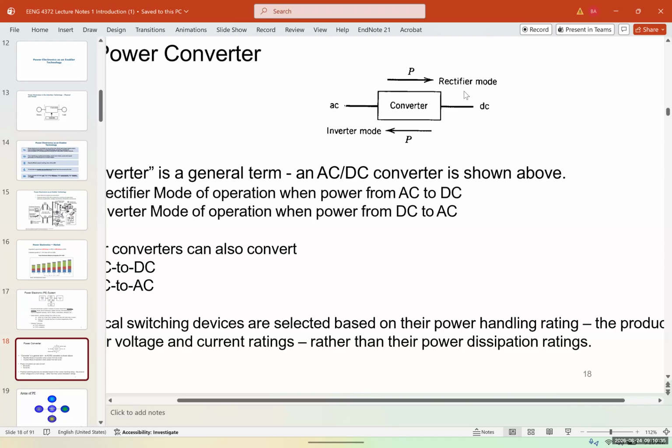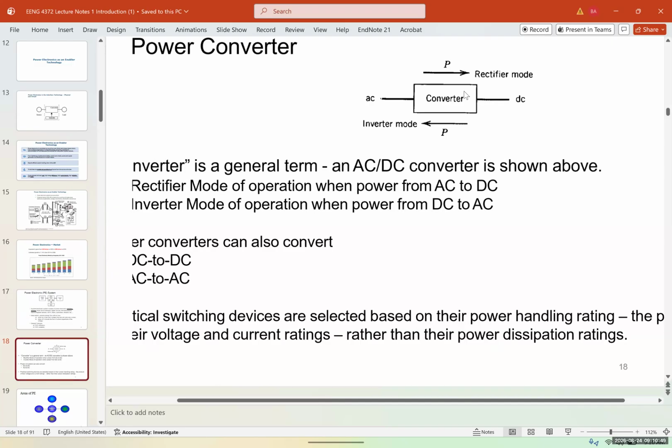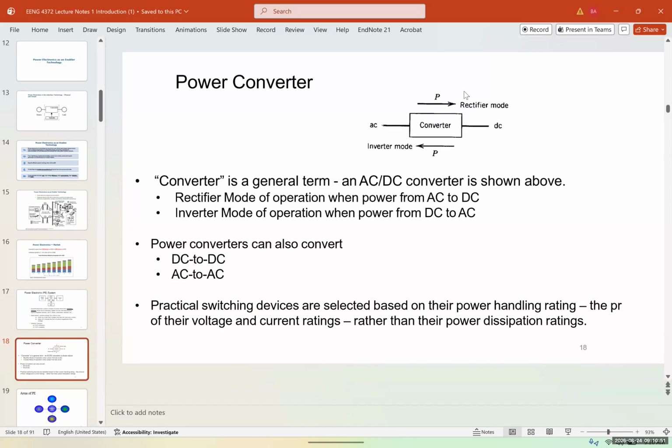And they have built it into a pack, so if you open a Tesla motor, you can see that the inverter is on top of the motor. So it's like a single unit. And obviously they have a single gear reduction. They don't even have a gearbox. So it's going to be very, very reliable.